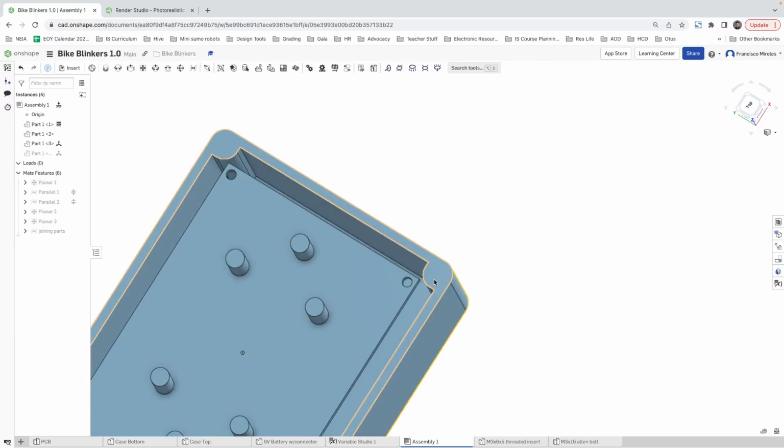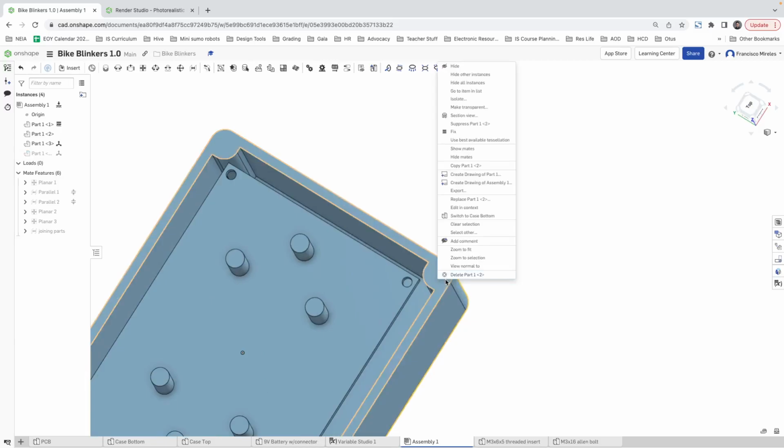And now I'm gonna do it here. Now my threaded insert is 5 millimeters. I think I'm gonna do a 4.8 hole, or maybe a 5, or 4.9. Just a little bit small so that I can melt it in.